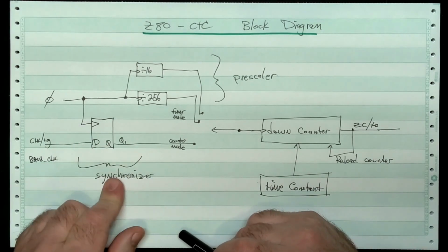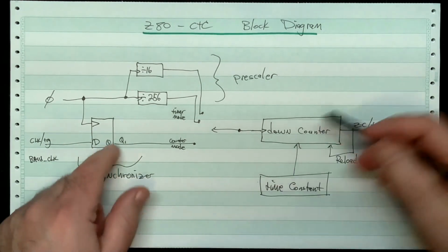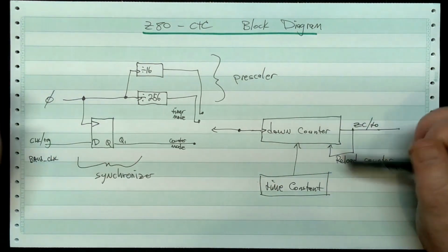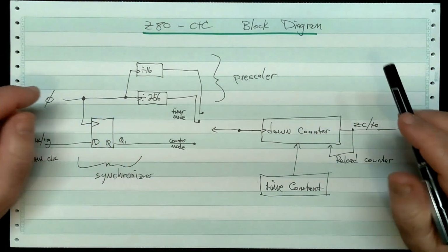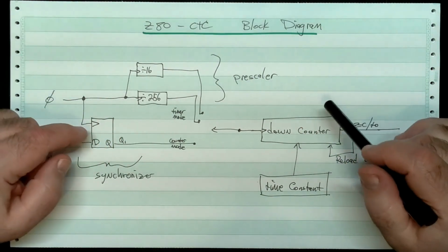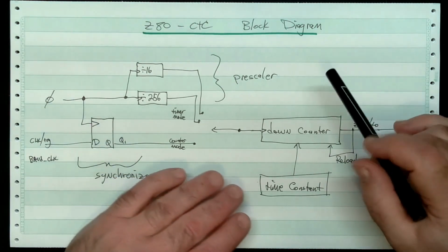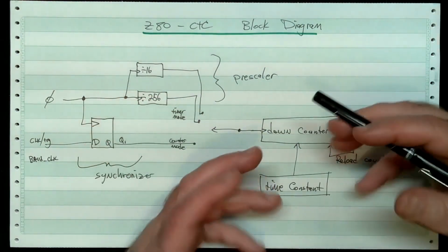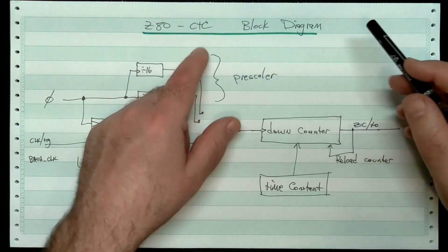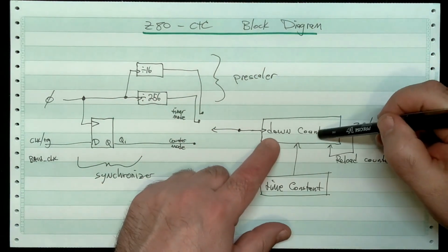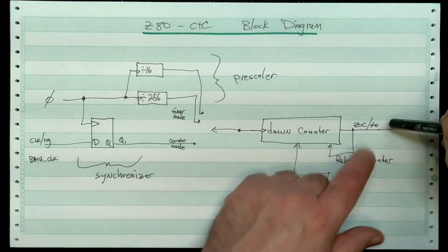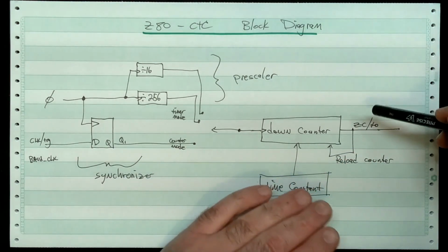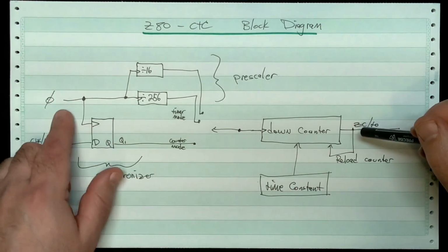So why is this here? What's this doing? If it all works great, if we just connect this up to the down counter. Well, there is some part of the problem with reality sets in, okay? So it turns out that in order to keep the timer running and doing all the other things that the timer has to do, the circuit, the CTC chip as a whole, the counter and all the interactions with this, that when the outputs go high and low, are to be synchronized to the main system clock up here.